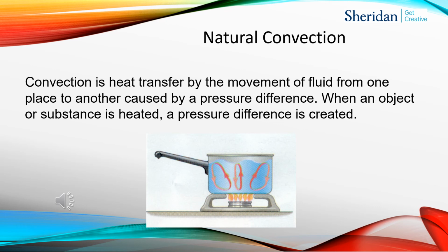The amount of mass or weight per any given volume becomes less, and in the case of the pot here, we see this lighter material wants to float. It flows up to the top, and the colder material at the top flows down to the bottom. What you have, as illustrated in the pot, are circulating currents, and the mixing of these molecules in the circulating currents is a transfer of heat.